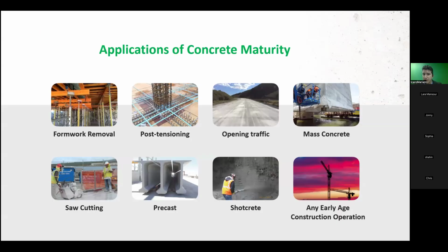In terms of applications, where can we use this? Literally in a lot of places. Mass concrete, opening traffic, post tensioning, formwork removal, even saw cutting. When you want to cut to provide your construction joints, you need to pinpoint, okay, I have 500 PSI there. You can actually use sensors to pinpoint that for you.